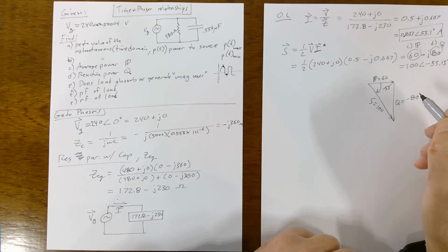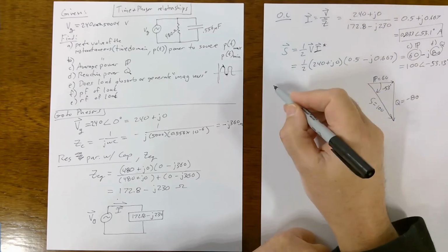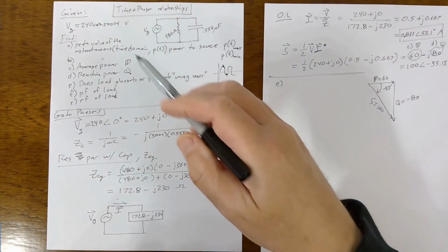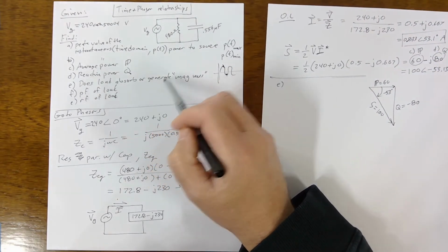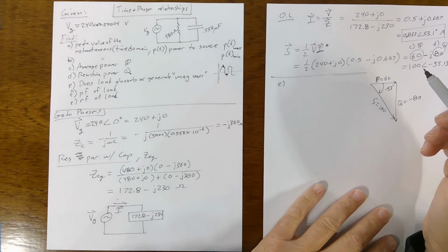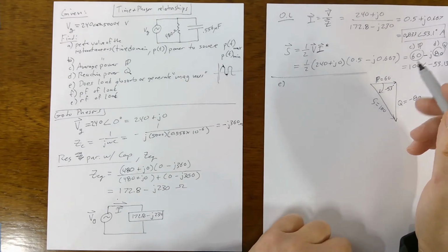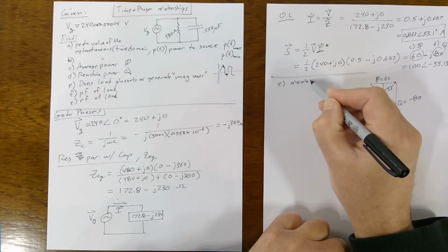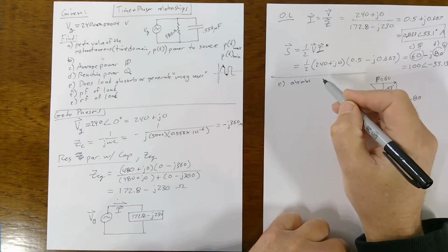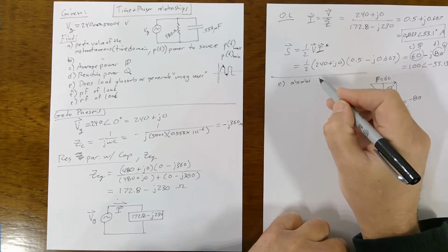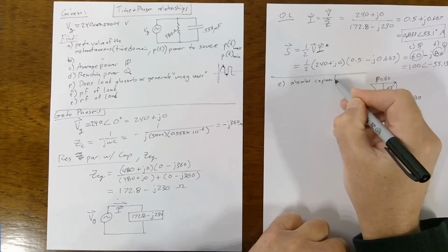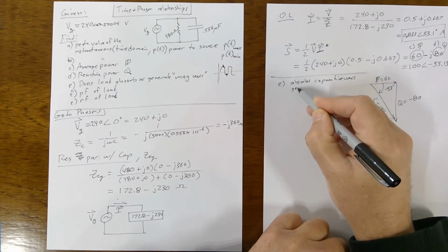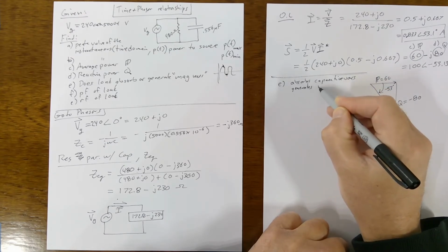Okay. We can answer part E. E is, does the load absorb or generate magnetizing VARs? And the answer is yes, it absorbs. Well, you could say that it absorbs capacitive VARs, or it generates magnetizing VARs.